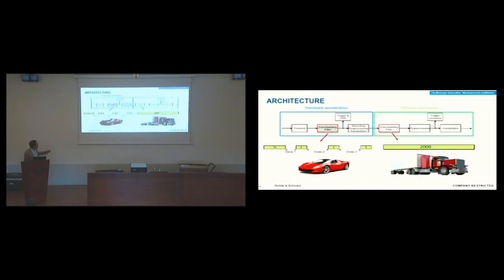So again, in this case, we should be able to do this differential math in this block here in hardware. In the ASIC of the oscilloscope, this is done in real time. So we can perform the differential signal, we can apply hardware clock data recovery in real time on the differential signal, apply de-embedding and filtering on this, and triggering on this, sorry, on this de-embedded, differential, and clock data recovered signal.